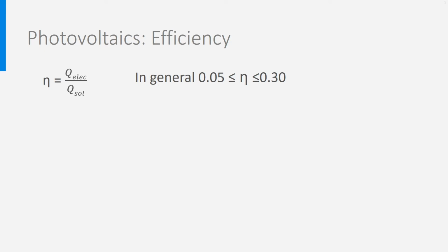This low efficiency comes, of course, from energy losses. To dislodge an electron from the P junction, a very specific quantity of energy is needed. If you give more than needed, this additional energy is just lost, as the electron cannot use it and just takes what it needs to jump. If you give less energy, all of it is lost, as the electron cannot use it to jump.